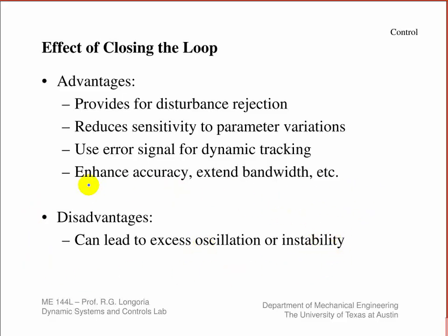One of the disadvantages of feedback control systems, aside from cost, you're adding sensors, you're adding more complexity, and you're having to design a controller and so on. So there's cost, but the critical thing is one of the influences of closing the loop is that you now make it possible, if you don't tune it correctly, that the system could become unstable. Whereas you might have initially had a system that was stable, you might make it unstable through the control that you design. So that's why so much time in controllers is spent trying to guarantee that it's stable and designing it properly. Okay.